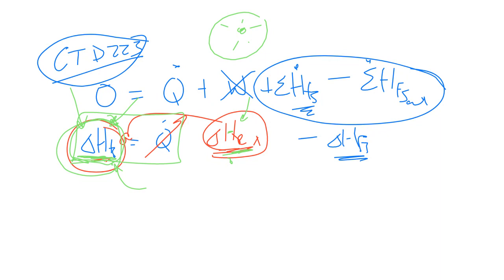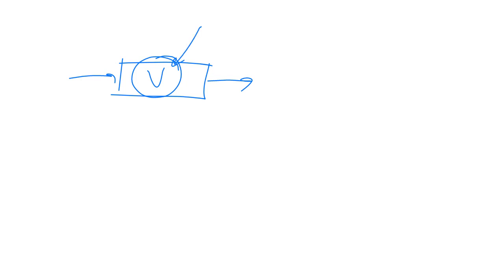The del H of the reaction is in there, and that is in those steps that we choose our convenient path. So we choose the delta H path. What Aspen cannot do for you is if you have to design a reactor. Aspen cannot design a reactor, and by designing it means sizing it. And now at this stage, I hope you realize that sizing a reactor, designing a reactor, is much more than just specifying the volume or the amount of catalyst.